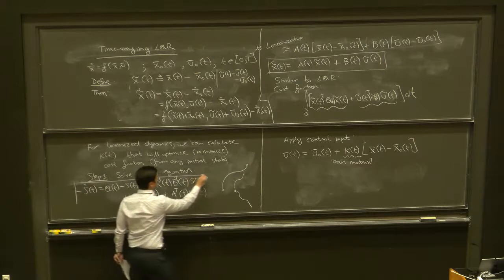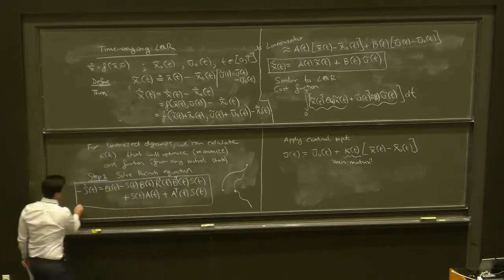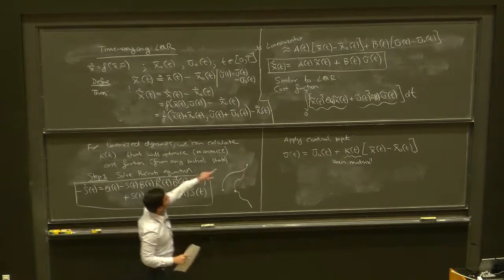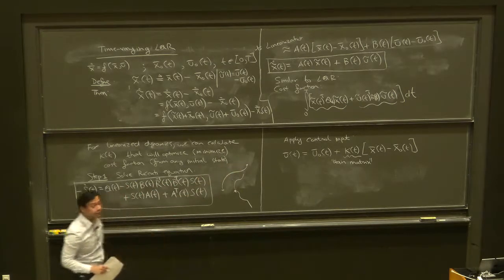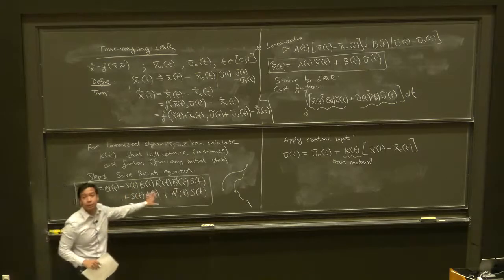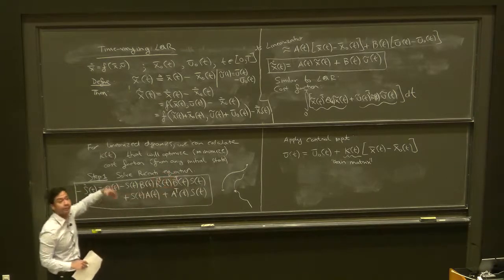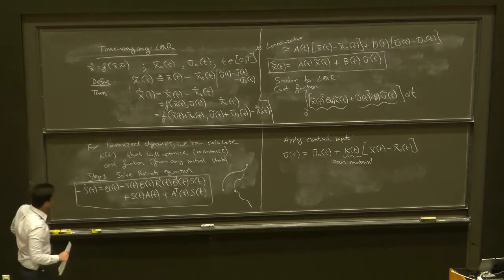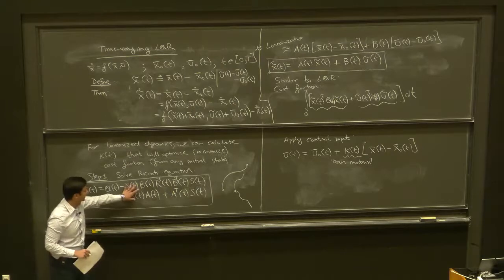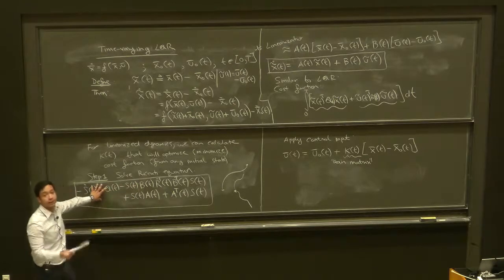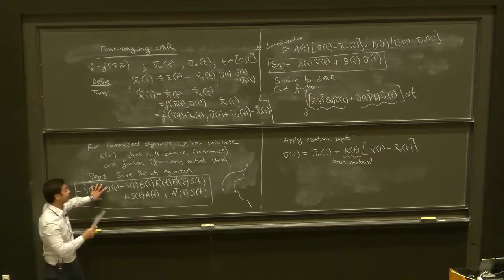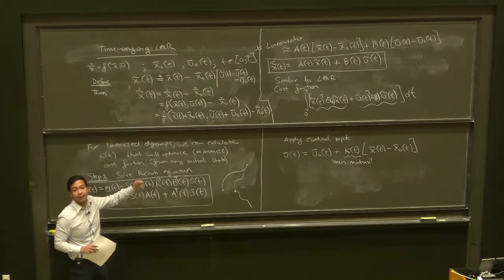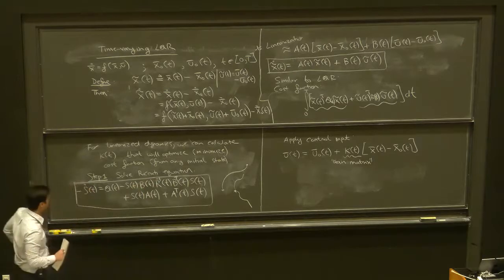So everything here is known. So Q of t, R of t, those are the matrices that define the cost function over there. A of t, B of t, those are the matrices that define your linear, time-varying linear dynamics that you get from the linearization process over there. The distinction between this equation and the previous version of the Riccati equation we had discussed when discussing LQR is, one, that everything is time varying, right? The A and B matrices, potentially the Q and R matrices as well.